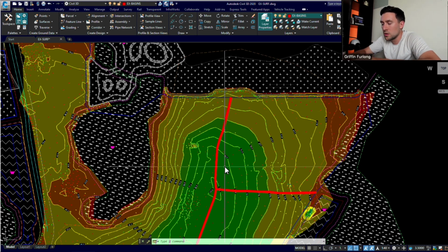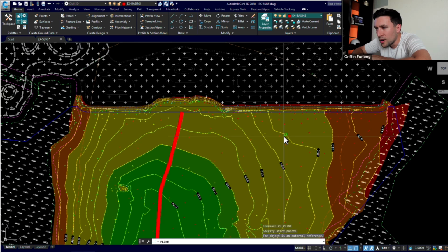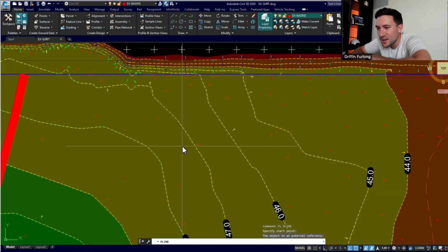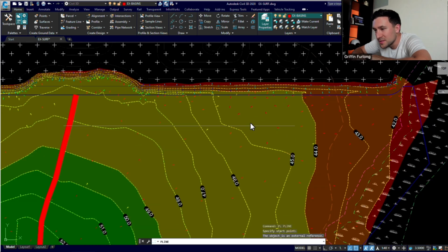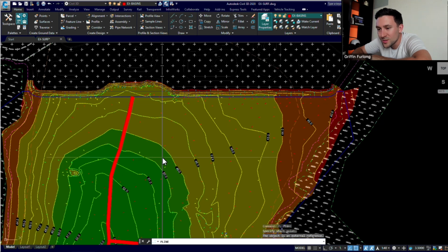So I'm going to draw another polyline just to see and map this out. Maybe we can arrive at a particular point here. Also, we put on a pretty cool style that shows the flow arrows, so sometimes that can even help us out. But I wouldn't always rely too much on those arrows, because sometimes those can get pretty wild. There's almost just a point right here. There's a small ridge where these contour labels are, where pretty much any water on this side looks like it wants to flow to that wetland. So I'm picking up on that, and to me, it feels something like this.